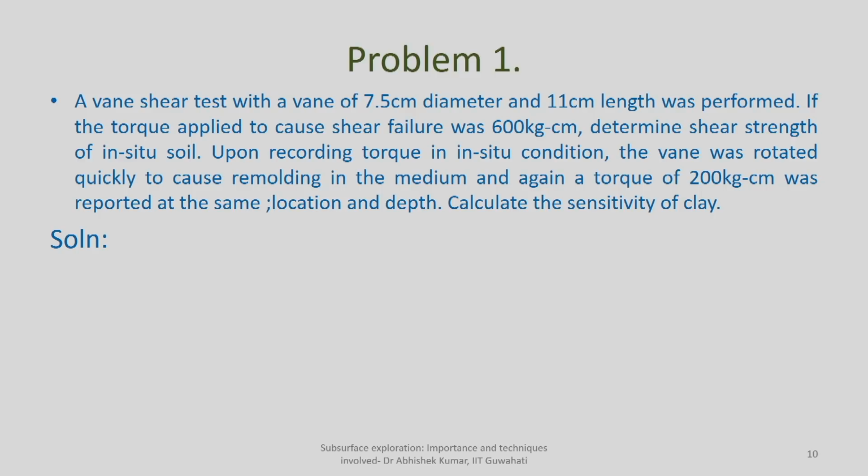another numerical, like how the information given from field investigation can be helpful to determine the shear strength properties. So here is one numerical which says a vane shear test setup with a vane of 7.5 centimeter diameter and height of 11 centimeter length was performed. The torque applied to cause shear failure was 600 kg centimeter. Determine the shear strength of the in situ soil.